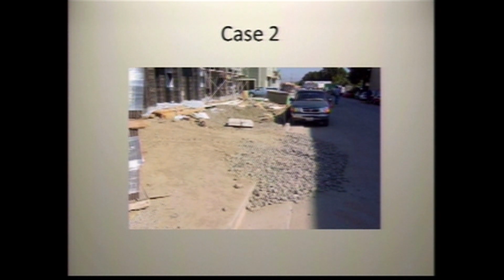It's a rock pile in the gutter. Yeah, that's a problem really, right? Because there's no track out control beyond that. So everybody leaving this part of the site, the dirt that's on the tires is going to be knocked out in that rock pile, which is right in the gutter. So that was probably put there because they thought they were doing a track out control, and to keep the curb from getting marked up. But it's actually depositing pollution right where water's going to flow, so it's something that needs to be corrected.